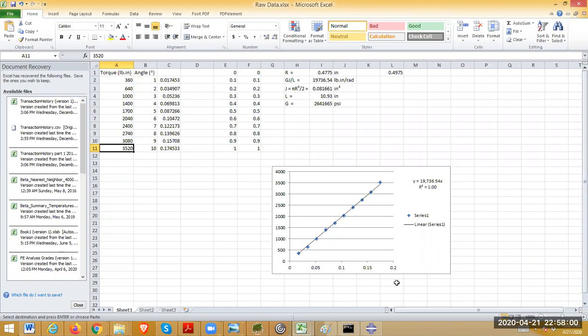That's right. So make sure that, I think there were two cylinders. One of them was only half a foot long. Make sure you're using the data for the cylinder that was about 1 foot long. The other smaller one was only half an inch in diameter. I don't remember exactly which group did the large cylinder, which group did the small, but use the data for the large cylinder. And compare the angle of twist. So that is the first question.